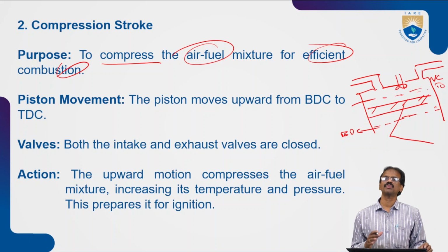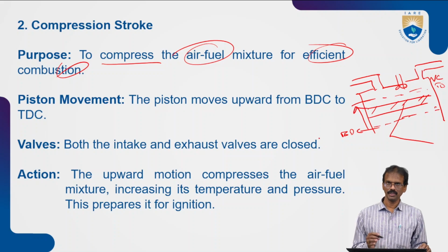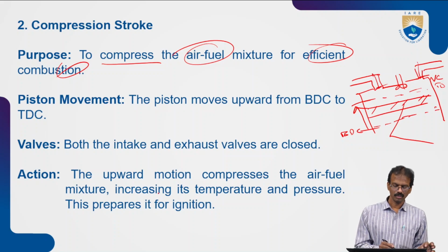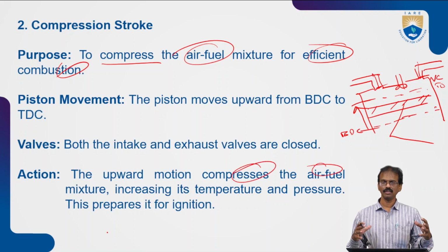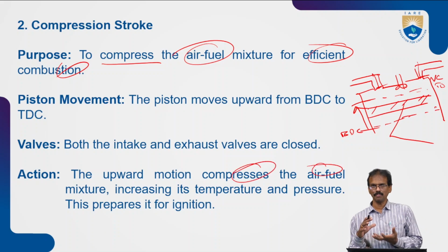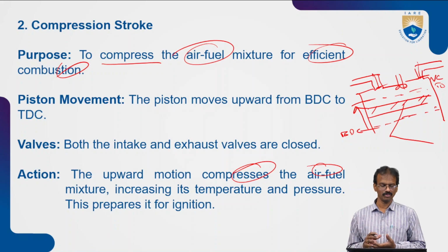In which the piston moves from bottom dead center to top dead center. So BDC to TDC. In this case, both the valves, inlet valve and exhaust valve, are closed. The upward motion compresses the air fuel mixture, and when it compresses the air fuel mixture, automatically the temperature and pressure will be increased. So this leads to pre-ignition, or just preparing for the ignition.